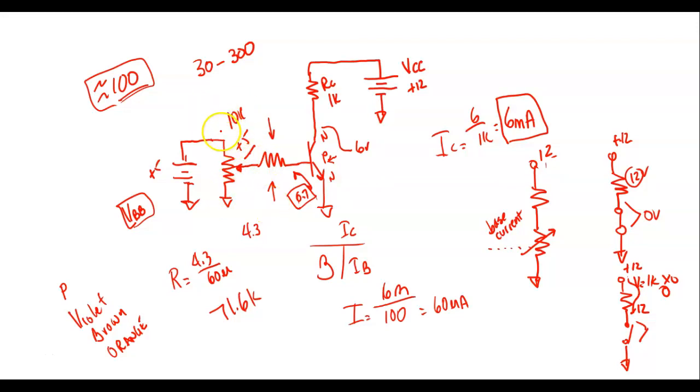So right now, I could get any voltage between 0 and 5 volts out of that pot. And that's what's nice about a pot. From the top to the bottom, you can get any voltage you need between those two ranges. Now, of course, we're not worried about current right now, right? That makes sense? Any more questions?